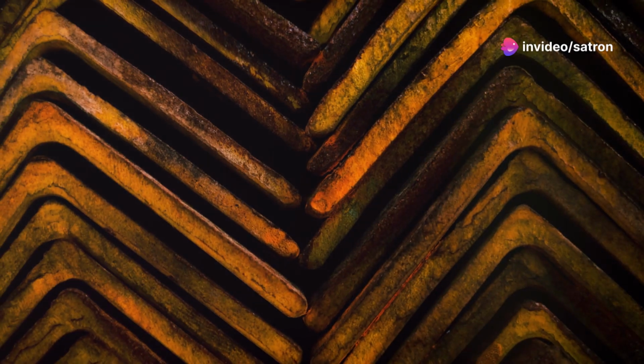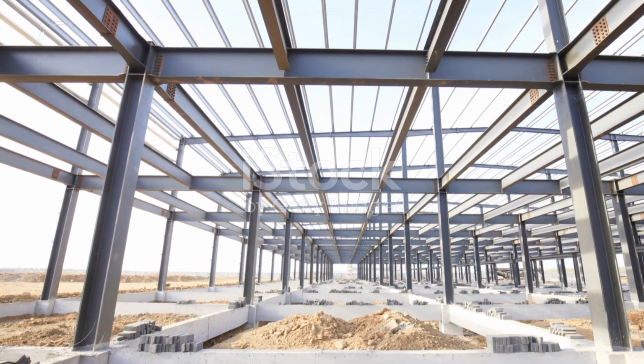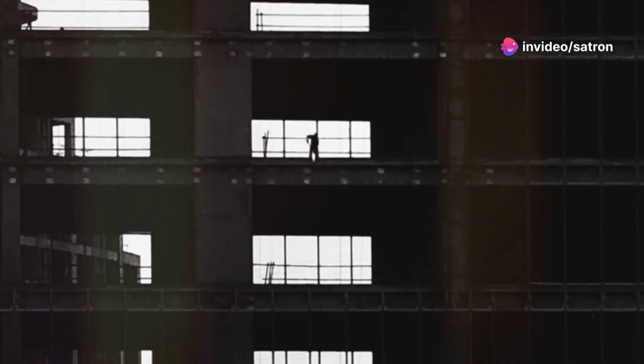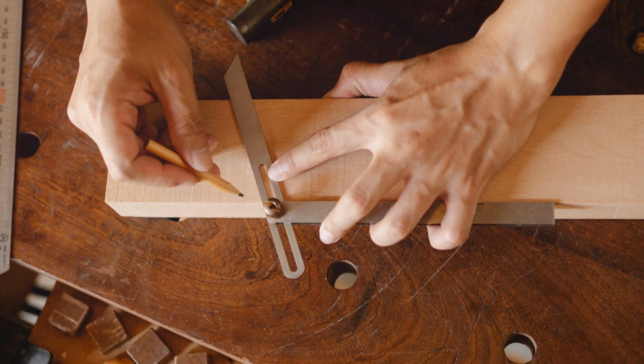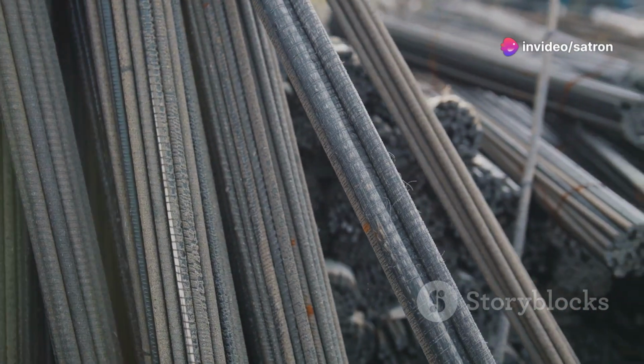Okay, maybe angles aren't the most glamorous members of the structural steel family, but they're the unsung heroes that hold everything together. These L-shaped pieces of steel might seem simple, but they play a vital role in countless structural connections and supports. Imagine you're building a steel frame. You've got your beams and columns in place, but how do you connect them? That's where angles come in. They're often used as cleats or brackets to connect different members together, providing additional strength and stability.